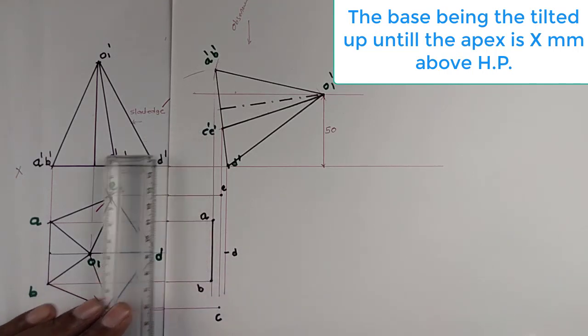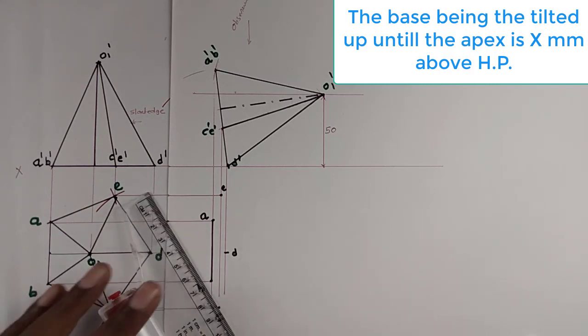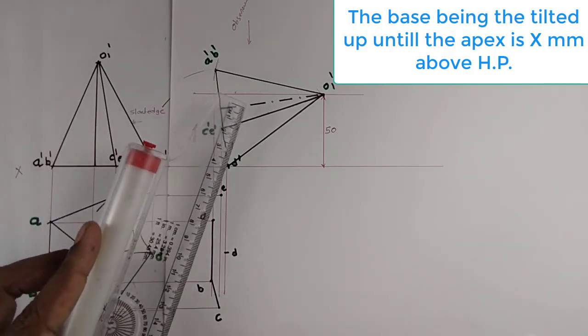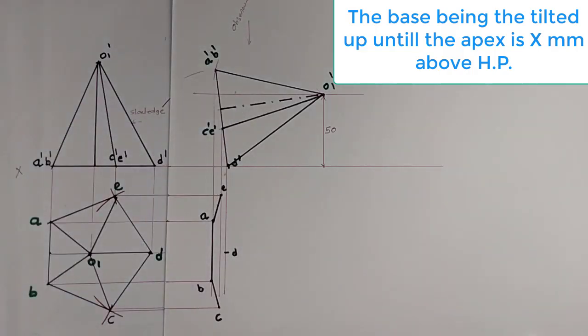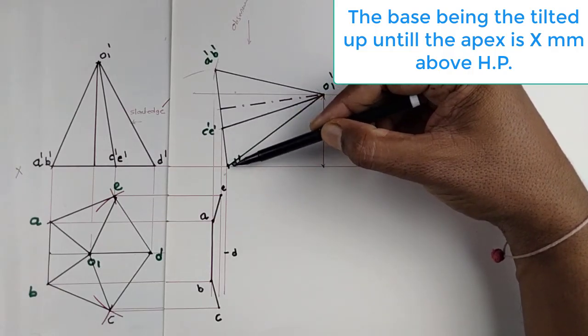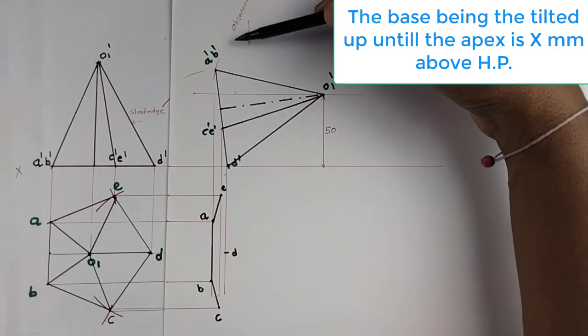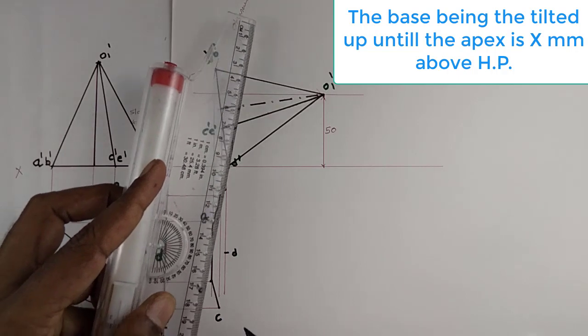AB is dark. Similarly, BC is also dark. AE is visible from top view, so it is dark. But the edges of the base, C dash D dash, D dash E dash, are not visible from top view, so we can show them as dotted.